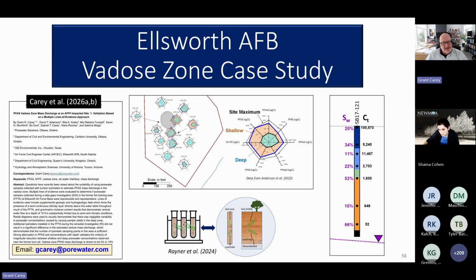this site at Ellsworth Air Force Base has had 2 different sets of lysimeters installed and samples collected for pore water. And they've got co-located samples for soil at each lysimeter. The second set of lysimeters installed for the RI also had co-located SPLP results. So they took soil samples and did SPLP tests at each RI lysimeter, and we can directly compare the SPLP leachate concentrations to pore water for all these different PFAS constituents, short chain and long chain, to see how they compare.